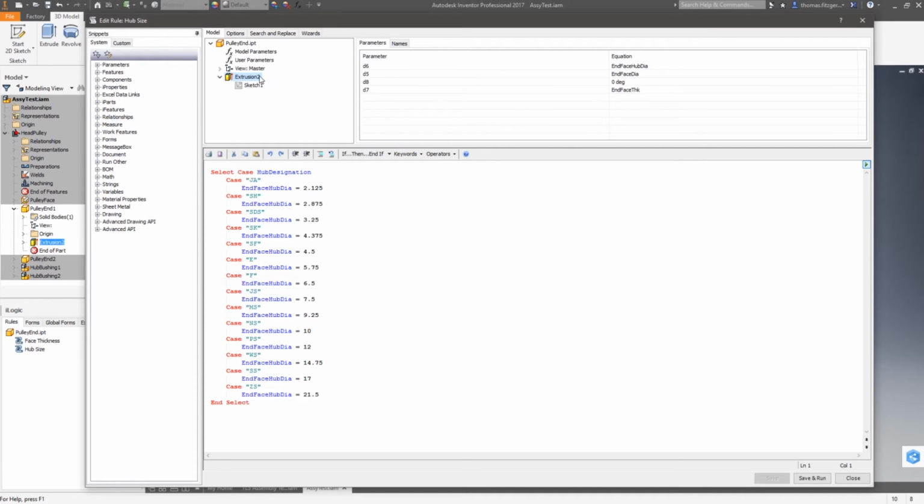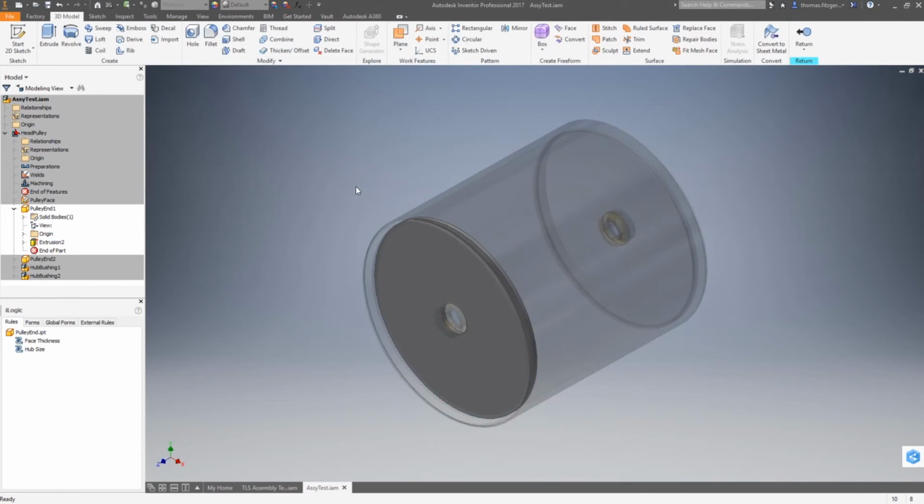You can give logical names to differentiate your features, because as you start perusing and drilling down into these features, you're going to want to access specific information. If you have a huge model that has 14 different extrusions named 1 through 14, it's very hard to understand what it is that you want to potentially manipulate later on. Okay, so static files, just good design practice.